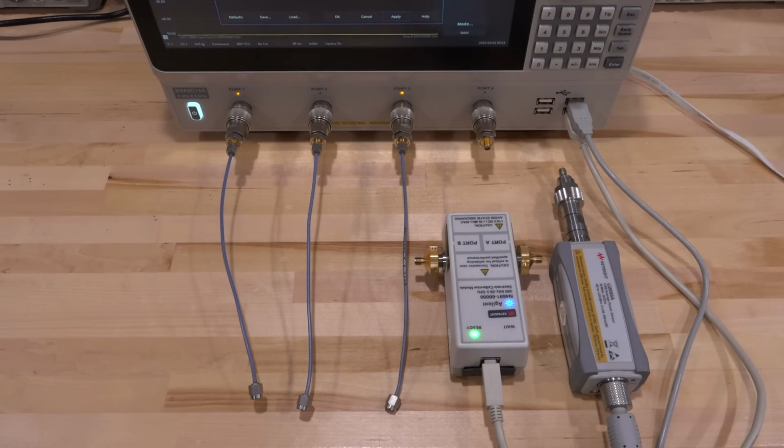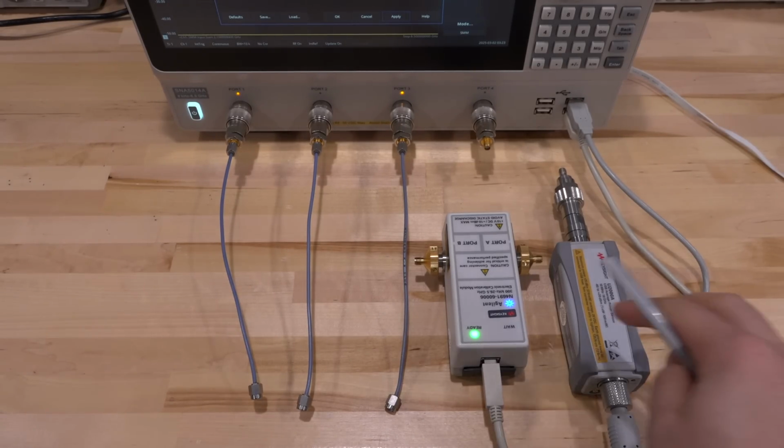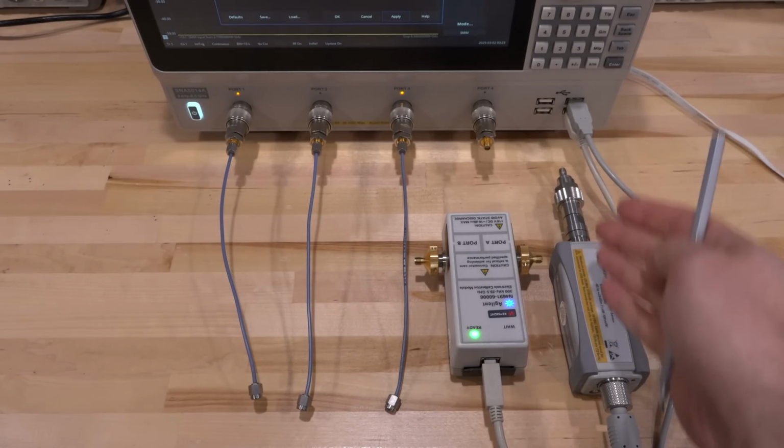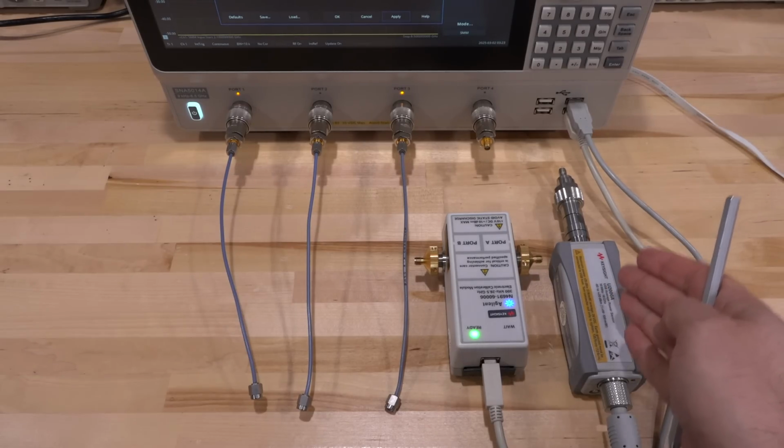That is really helpful. Now, remember that a network analyzer is never measuring absolute values of anything. Network analyzers are always making relative ratio measurements. As a result, the exact power coming out of the port and the exact measured power going into the port is not very critical. Only the relative ratio is important. And if you really want very accurate power conversion measurements where you are making absolute measurements like a mixer, you need to do a power cal on top of that.